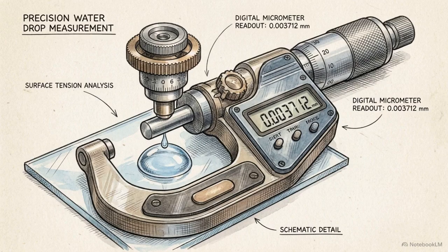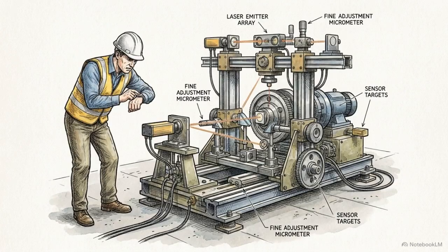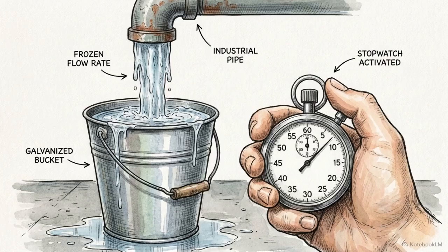However, auditors must avoid the trap of over-precision. Chasing extreme accuracy wastes valuable field time when simple tools are often enough to draw the correct conclusions. Sometimes a bucket and a stopwatch are all you need to accurately measure a fluid flow rate.